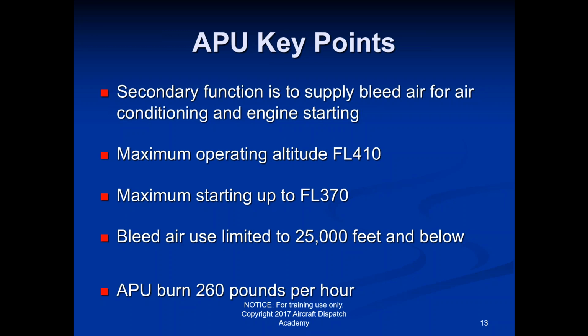And the way that works is the APU will get turned on, and it's turned on just electrically. So if the APU is functioning, then the pilots can, let's say they just walked into a plane that was sitting there overnight, it didn't have any power on the plane at all other than just the GPU hooked up to it. The GPU is just the plug that they hook in from the jet bridge, that they plug into the nose of the plane. That just gives electrical power, but that electrical power is coming from the ground, from the airport. So the only thing the APU needs in order to start is just ground power. So as long as you plug in the GPU to the aircraft, then the pilots can get in the plane and fire up this APU, and the APU is located back in the tail.